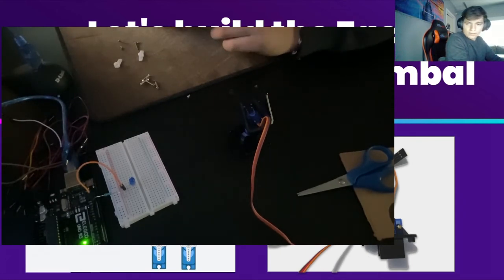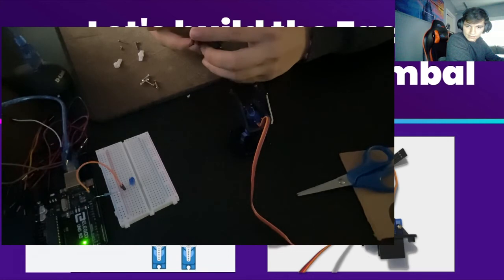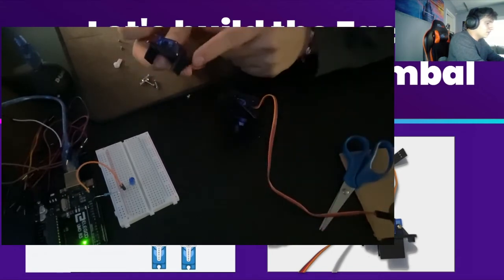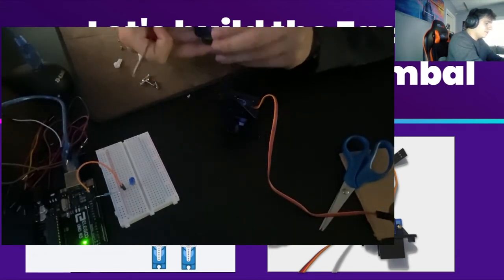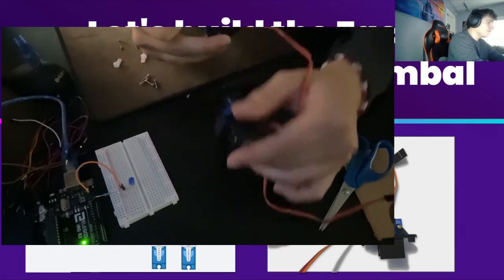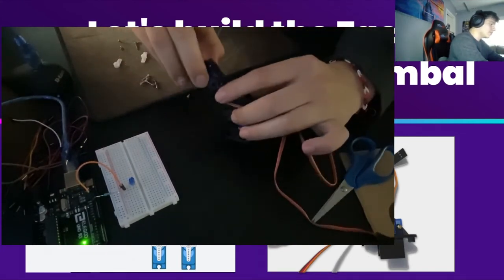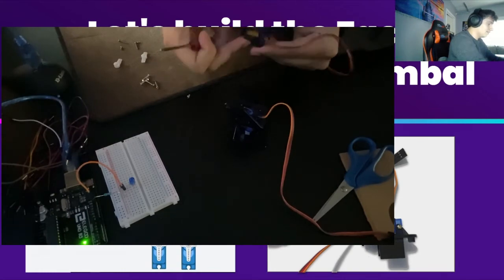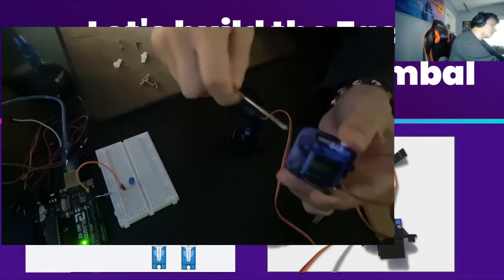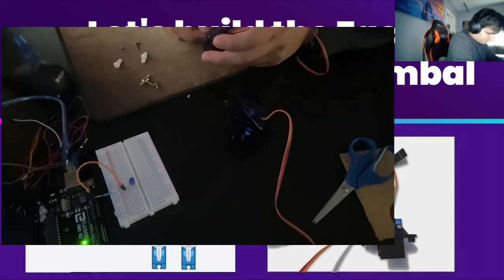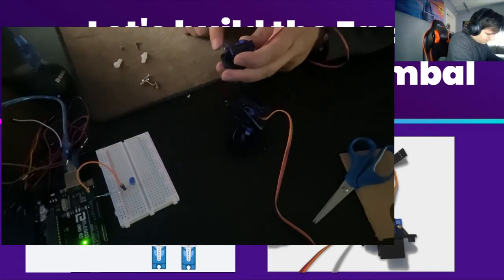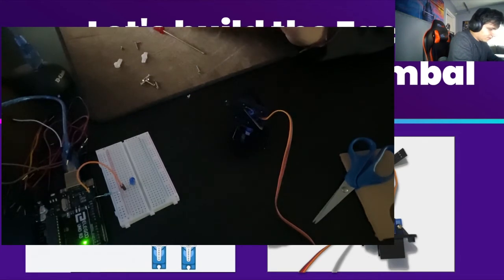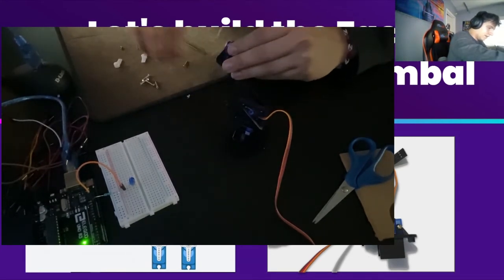But so now we're gonna put the servo. So let's see how this goes. We see here that this has a little bump right here that's supposed to go in this part right here, and then we have this white part of the servo that's gonna go through this hole. So then we know that it's gonna go in this orientation. In that case, all we have to do is put the servo like this, facing this, and then put the screws through there. I'll speed through this if it takes too long, just so you guys have the correct idea of how this thing goes.